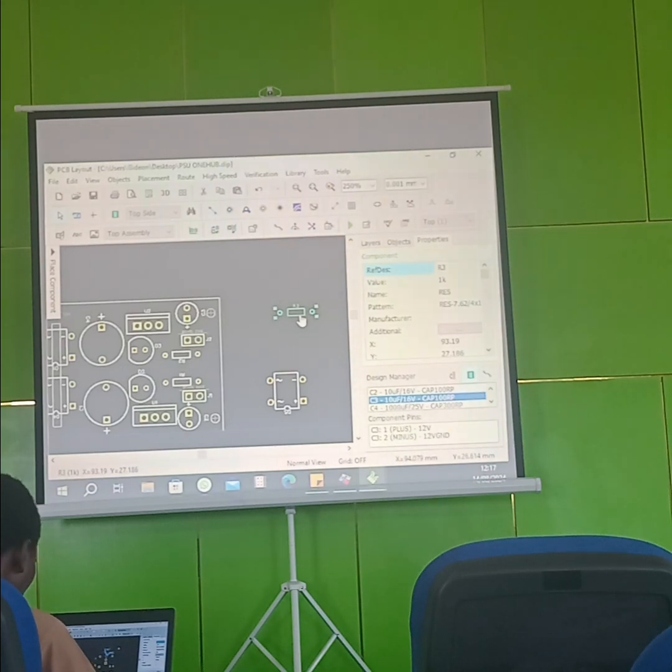You understand that? Sometimes we don't want to stress our pick and place machine, or sometimes it will just calculate: is that 180 or 0? So if it is taking 360, we don't want to stress the nozzle. Because the nozzle will pick it and still rotate it, even though it is the same polarity. So that's what we call optimization in pick and place machine.